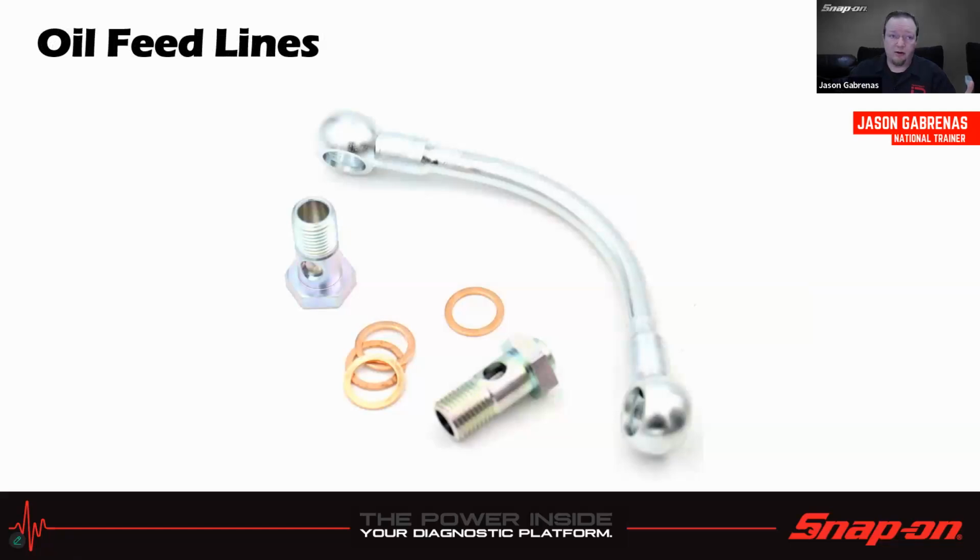And then we also need, of course, to be able to get the oil to this because it's oil actuated. So we need oil feed lines as well. So oftentimes you'll see just the metal lines. Could be some rubber involved, and then of course you have these banjo bolts. Some of the banjo bolts will have a filter in them. Usually the ones with the little nub at the end are going to have some sort of a cleaning filter in there, just so no gunk and crud gets into the actual system itself or into the gears, or at least it tries not to get into the gears.